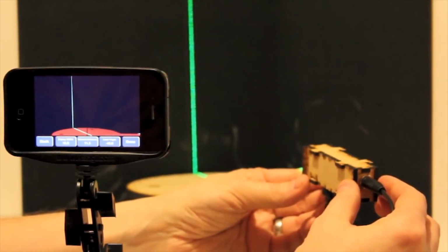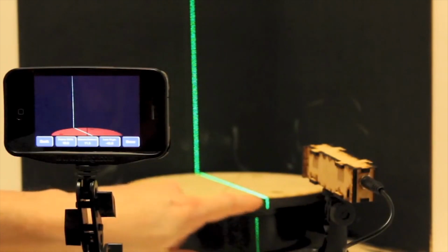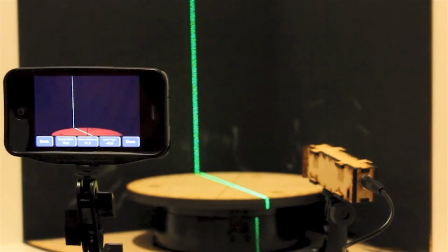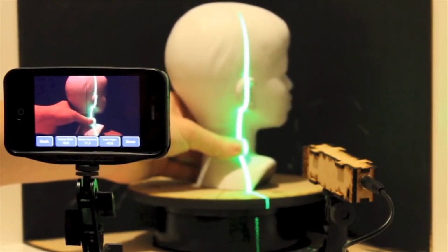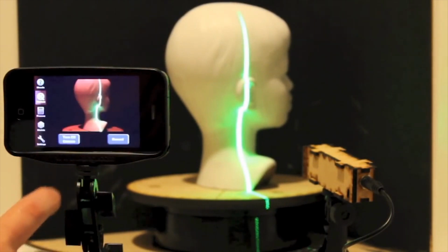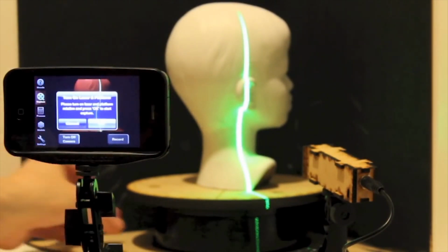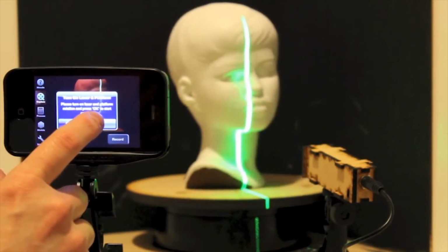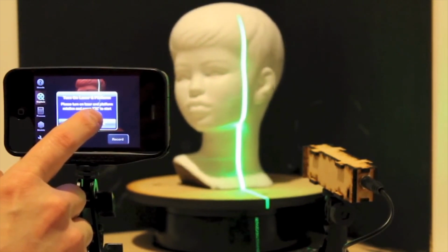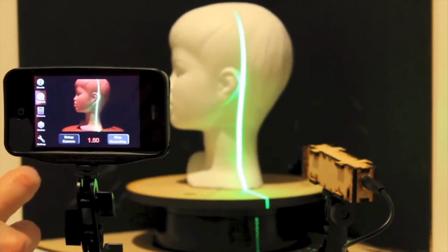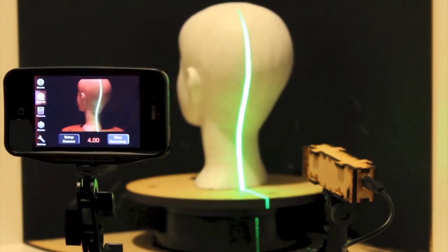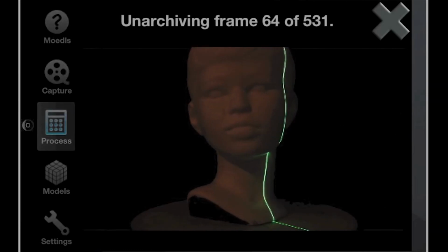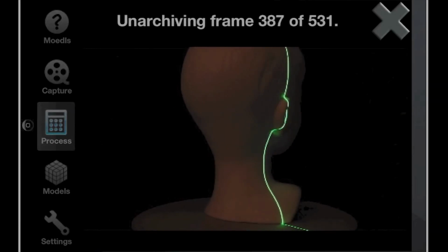Non-contact devices employ light within the data capture process. This creates problems when the light impinges on shiny surfaces, and hence some surfaces must be prepared with a temporary coating of fine powder before scanning. These issues restrict the use of remote sensing devices to areas in engineering where the accuracy of the information generated is secondary to the speed of data capture. However, as research and laser development in optical technology continue, the accuracy of the commercially available non-contact scanning devices is beginning to improve. The output of the scanning phase is point cloud data sets in the most convenient format.